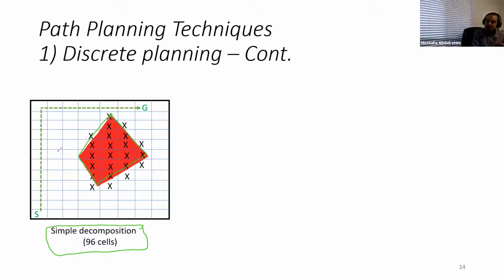So in our map now, if any of these grid cells is intersecting with our obstacle, this is a forbidden cell, and the robot should avoid it. Okay. So let's change the color, make it, for example, brown. Since this cell, although it has some free area, intersects with the obstacle, I will consider it all as forbidden.